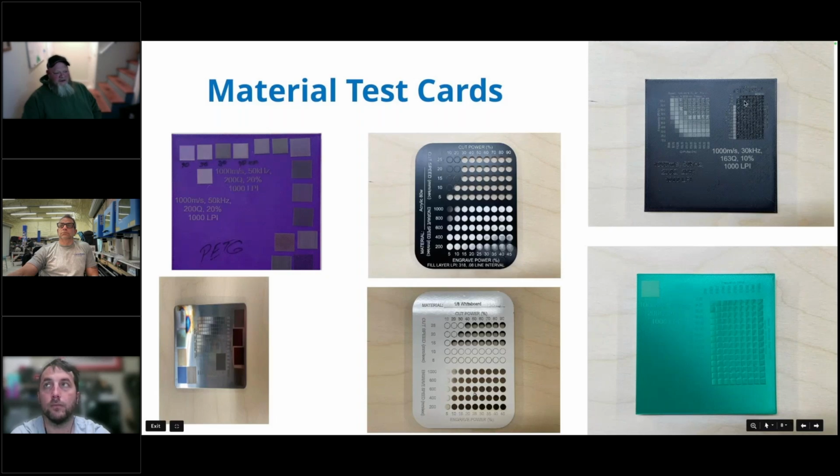And you can see here, when you're testing, I kind of goofed that one up and made it a little too hot, or a little too slow. Same way on this one and some of the other ones. The metal business card over here, I ran a test and got it a little too hot. And the test is on the opposite side, so the back side of it turned all kinds of colors because there was too much heat, because I hit the wrong settings.